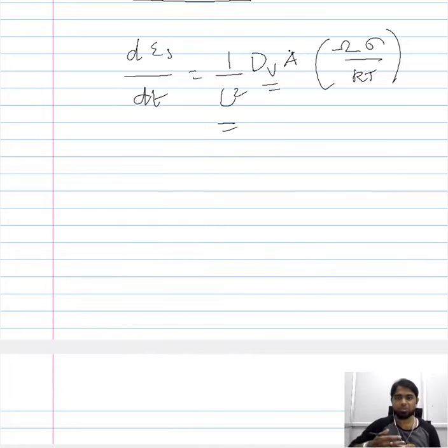This of course is a constant as it relates to the exponential of the energy required for the formation of vacancies and temperature, and the variable here is the stress. We have seen that this can be related to one form of the dislocation creep mechanism. Now this term here is the diffusivity of vacancies.